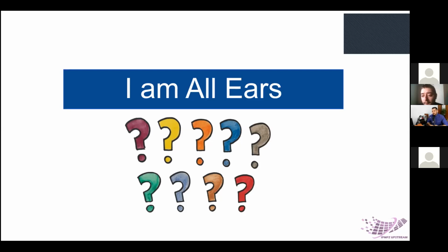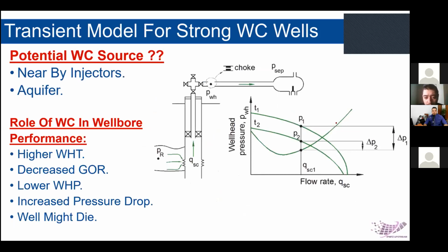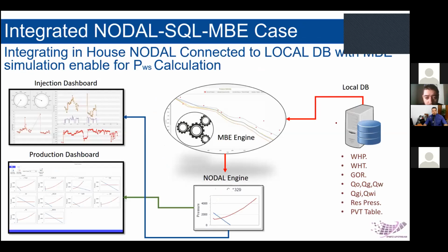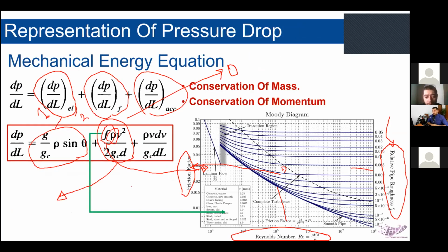If you recall, let me take you back to the pressure drop equation that I presented. This equation you can use for production or injection wells. The main challenge with the injection well is the absence of the flow rate, plus you don't have the bottom hole flowing pressure. In this regard, you have two routes you can go with. Either you have an injection logging tool that you have run previously. You can use that. You will have the Pwf and Q from that, and you can build a model.